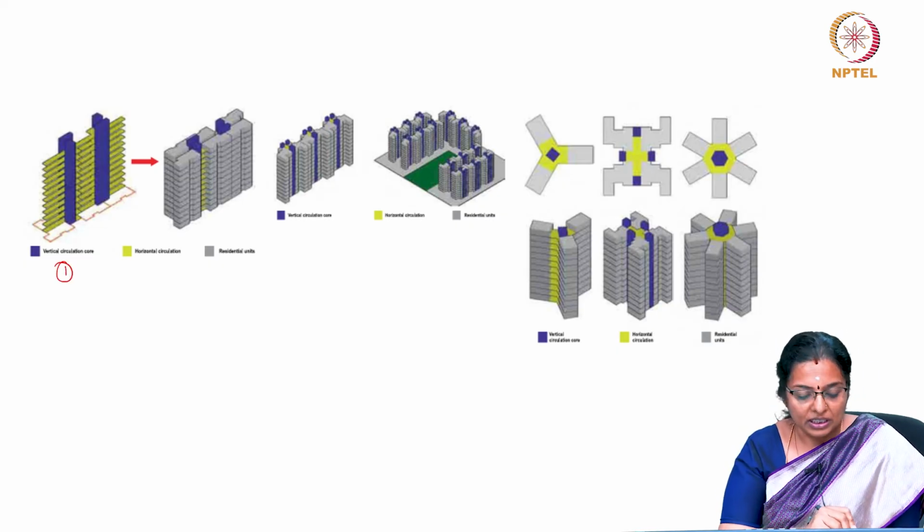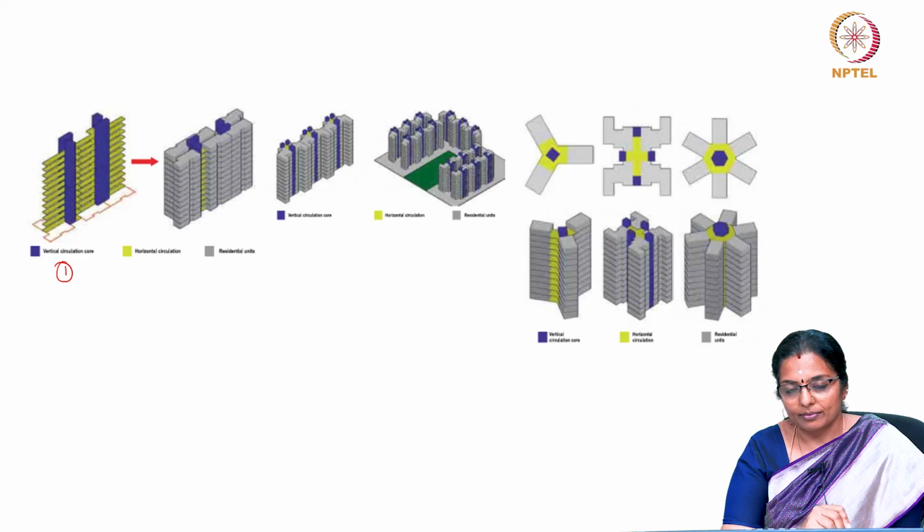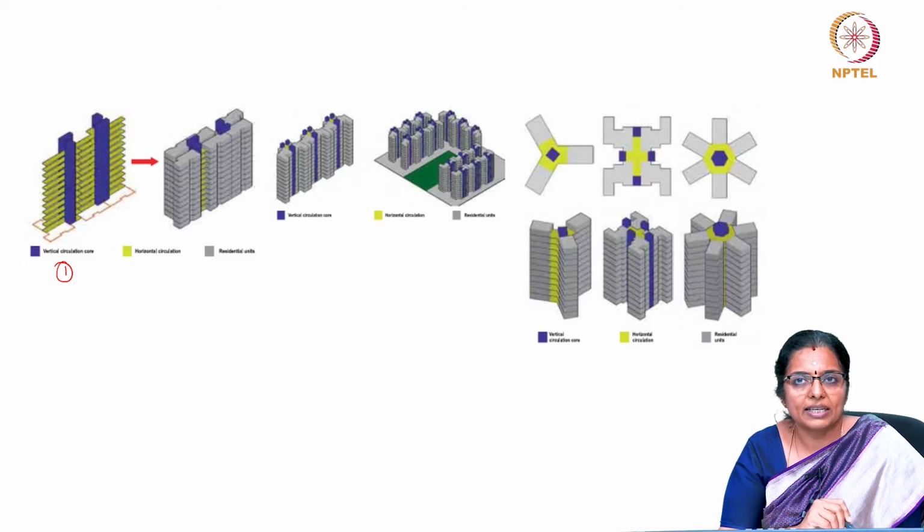Then you have a linear typology, and third you have a tower typology. So, the shape and volume of buildings should be compact, yet somewhat elongated along the east-west axis. Example, the optimum shape is probably in the ratio of 1:3 in hot and dry climates.